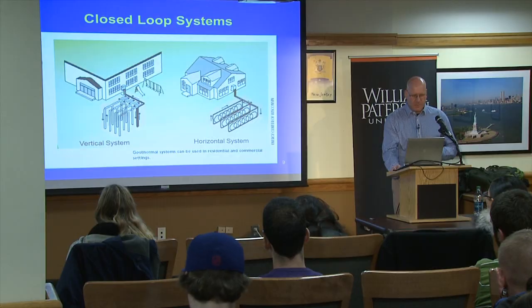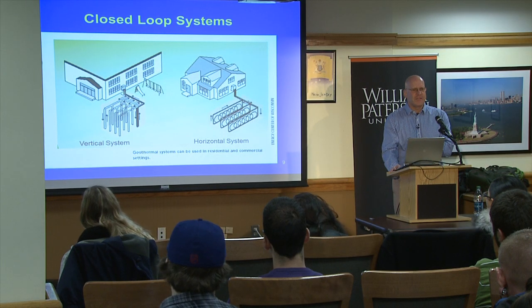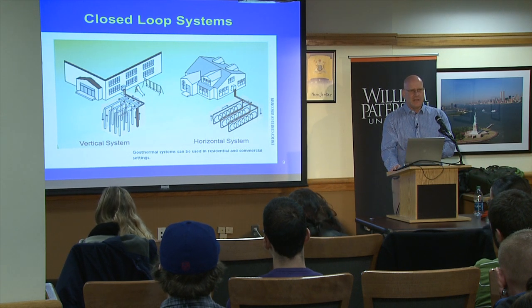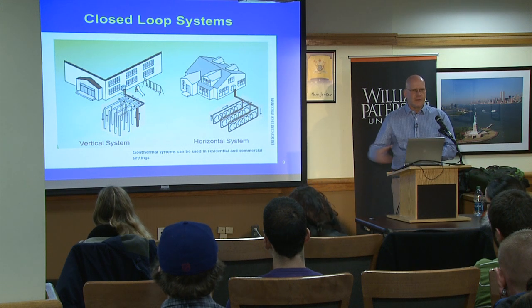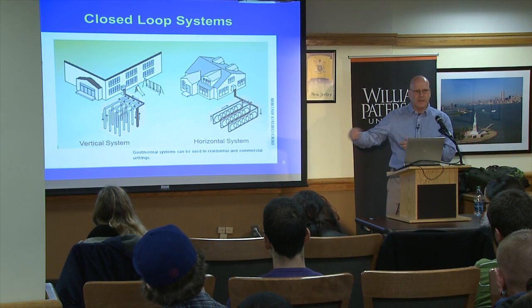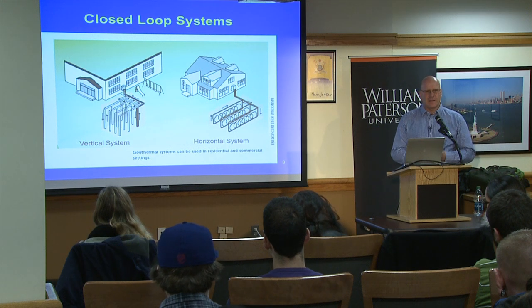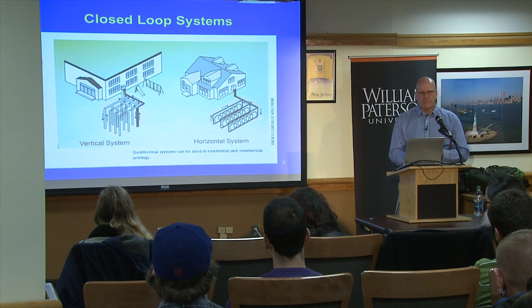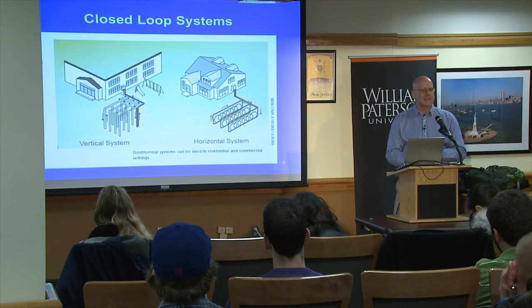So I talked about mostly vertical systems because of the land challenges here in the Northeast. In the Midwest, a farmer, if they have enough room, could just put 15-foot trenches and coil it as a means of getting more contact with the ground. And they have loose, silty sands out in the Midwest, and they could do it that way. And there are plenty of these systems out there.